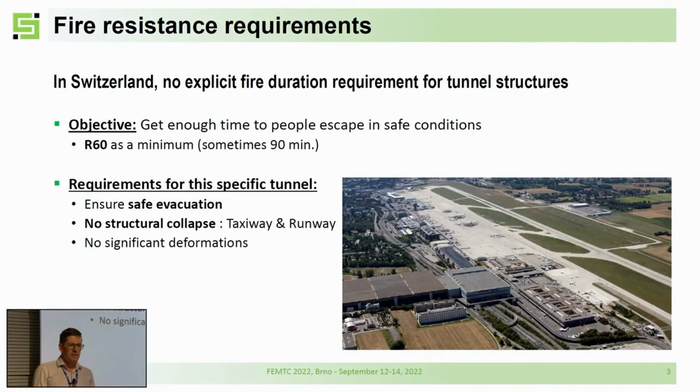In Switzerland, until 2004, there was no explicit fire duration requirement for tunnel structures. So by that time, we didn't know what to do with this project, and the requirement was often R60 or maybe sometimes R90 minutes. For this project, we have to ensure a safe evacuation and no structural collapse because the tunnel is under the airport, taxiway, and runway. And we should have no significant deformation.